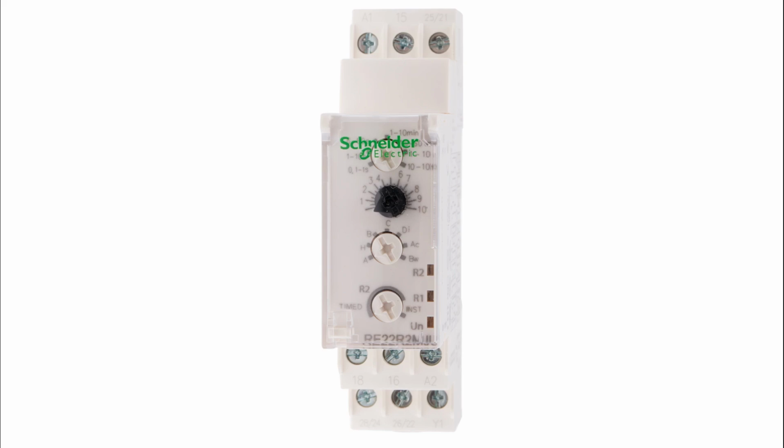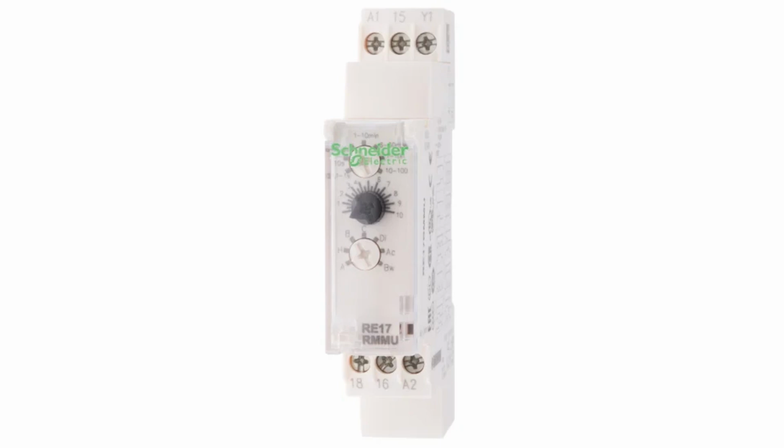In summary, the choice between solid-state and electromechanical time delay relays depends on factors such as switching speed, reliability, size constraints, environmental conditions, and specific application requirements. Solid-state relays offer fast, reliable, and silent operation with no mechanical wear, whereas electromechanical relays provide proven reliability and high power handling capability. Voltage and current ratings are essential specifications to consider when selecting a time delay relay, as they determine the compatibility and suitability of the relay for a particular application.